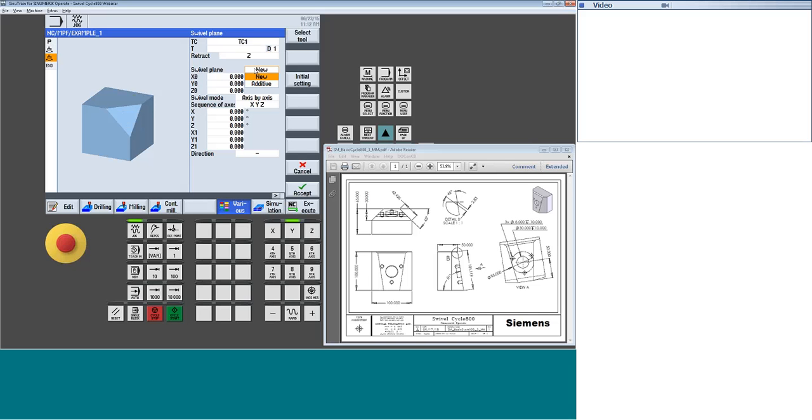So we want an absolute position. Do I want to stage my part 0? That's very handy when I start doing part programming, especially on the machine, because based on the dimensional data, when I do my rotation, I don't want my work coordinate system to be left somewhere in space, because I might not know from that point where my part planes or my features dimensionally are. So you'll find you move it around. On this first one, I'm going to leave it right here in the lower left corner, all right?